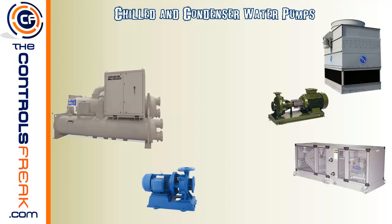We've already talked about the chiller here, and we've also talked about the cooling tower. Some other little items besides the pumps that we put here is the air handler. This is an example of a packaged unit air handler that would be inside the building, and you'll see the little pipe connections here, and that's the cooling coil that's inside the unit. This green pump is going to represent our condenser water pump, and typically they use green piping or green to represent condenser water. And then this little blue pump here is going to represent our chill water pump, and they usually try to use blue or white for chill water piping as well.